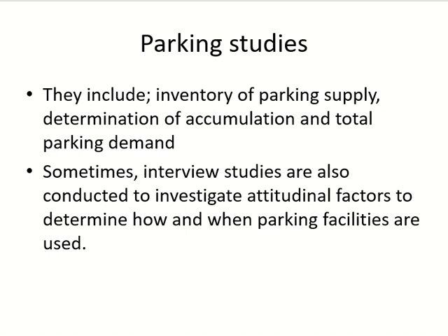Okay, so you have your own preferences, right? You have your own choices. So parking also depends upon the choice of the driver. There are some people who may park at some distance and they would like to walk, because they feel their parking space is under the shade and so on. And there are others who will say, no, I will park near the gate, even if there is no shade and so on. Got it? So that's why parking studies may involve interviews as well to the drivers to know their choices.